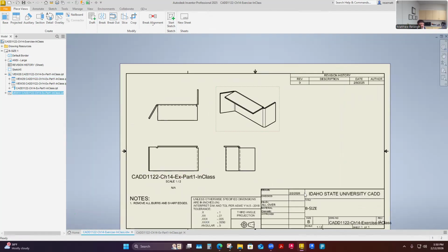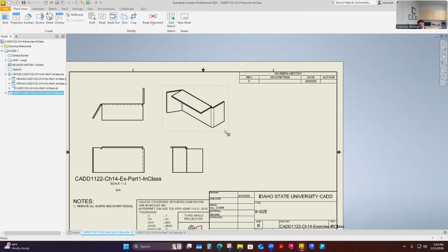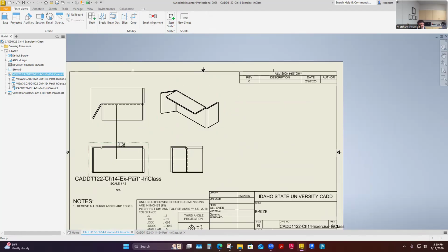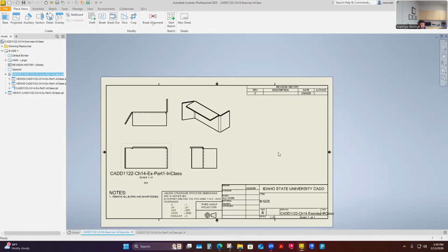And then what I showed is that, and I think he shows it, he does it on two different sheets and deletes one or whatever. I'm just going to say, you could drop that on there, and then I can drop a flat pattern here too. Normally my flat patterns end up on their own cut file sheets, maybe organized by material thicknesses and types. I might have multiple sheets with different materials of parts being cut, and I would want those to be their flat patterns. So I'm going to put this on the same sheet, but a lot of times these end up on separate sheets, cut files, and that's what I say a flat pattern is: a cut file.